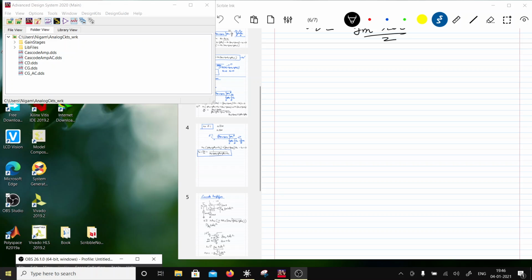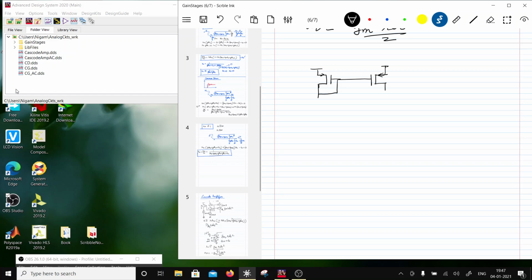The reason for the small input voltage range is that the DC is somehow coupled with the AC, so this has to be decoupled. Now the basic configuration goes like this: you have a PMOS which provides a current. This is diode connected, so it is going to force a certain current into the differential stage. And what is the differential stage? I'll just draw it out. You have a PMOS stage with a differential configuration like this, and then it has a current mirror load.